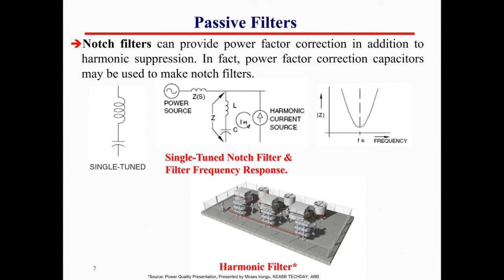Okay, this is another harmonic filter designed by ABB. So again, you can see the inductance over here. You can see the coil, okay. Then those could be the capacitor bank. And then of course we're going to have also some resistance placed over here. Okay, and again over here we are talking about the notch filter.